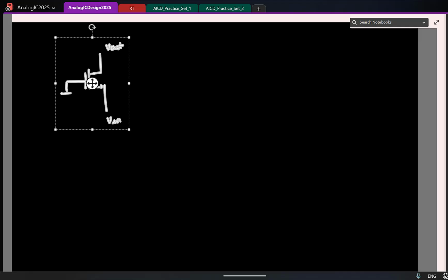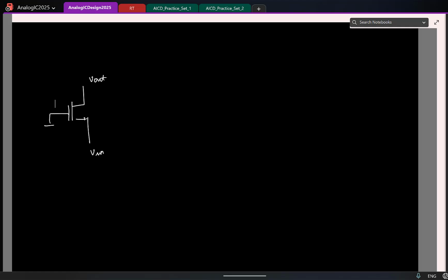So which means now my input is at the source, output is at the drain, right? So for small signals, my gate will be ground. So again, I'll just look at the small signal picture. Let us say I have Vin applied here, and let us say some RD or something here, and let me ignore R0 for simplicity.